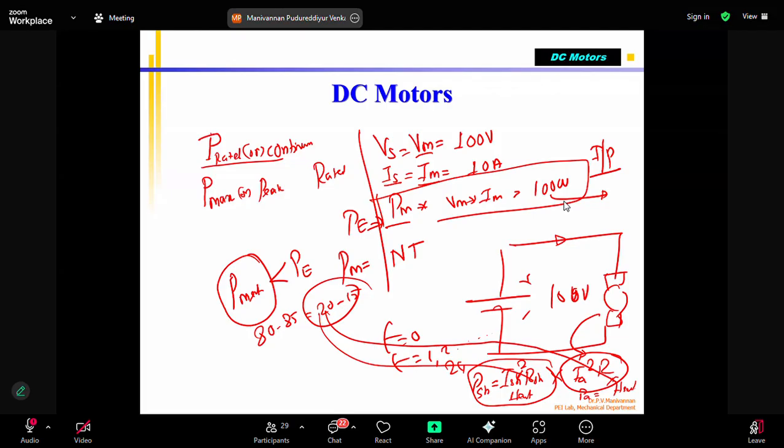You may supply cooling, because later I'm going to talk about various losses, power losses in your motor, when we talk about induction motor. Okay, maybe tomorrow, day after, that also. So these are mechanical power losses: friction in the bearings, and wind resistance, because air will be supplied inside the motor to cool it. You will see that internally it will be closed, and there will be a small fan to remove the heat generated in the coils.